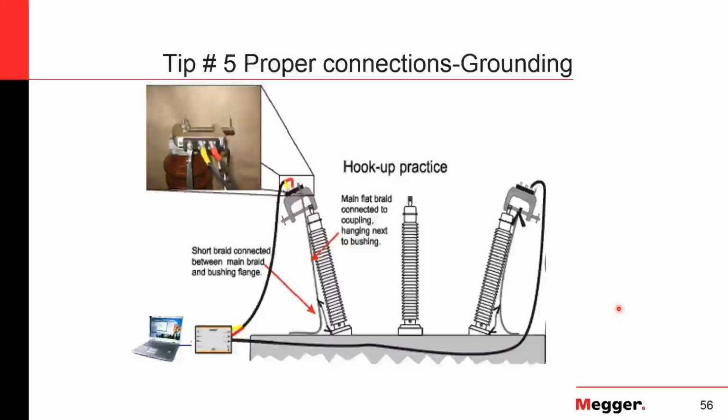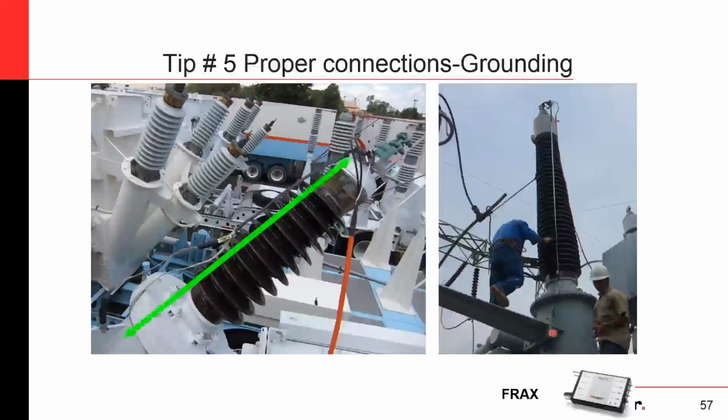Poor grounding is when you just have ground floating around, and this could be curled up or this could be laid out flat. And because the inductance of those loops change or the impedances change, it'll vary the results in that high range frequency. So by doing the shortest braided ground, having solid connections, you're going to have repeatable results there.